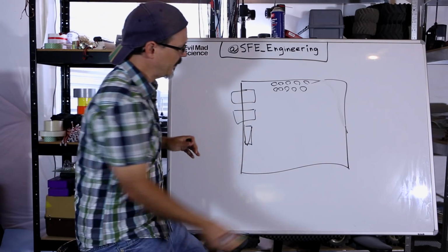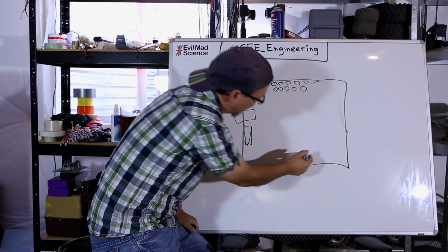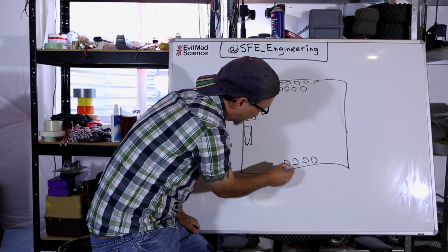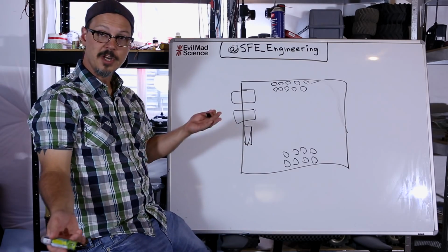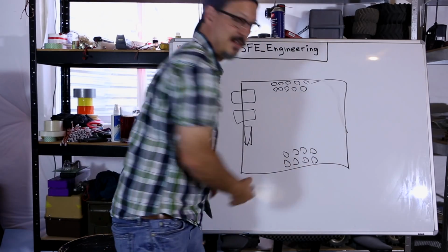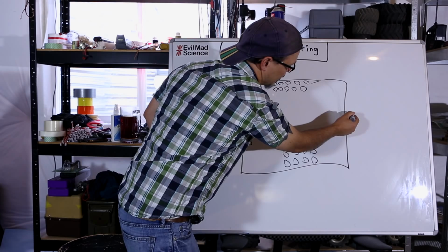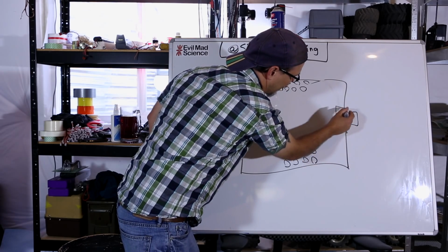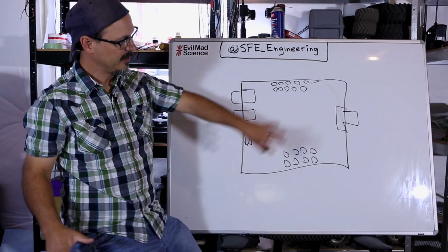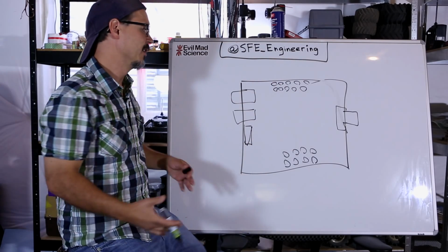So you might bring inputs over here, and you might put outputs over here. You might have an RF jack, for example, like an RP-SMA for 2.4 gigahertz. So that's going to have to hang off the side, sort of like yay.